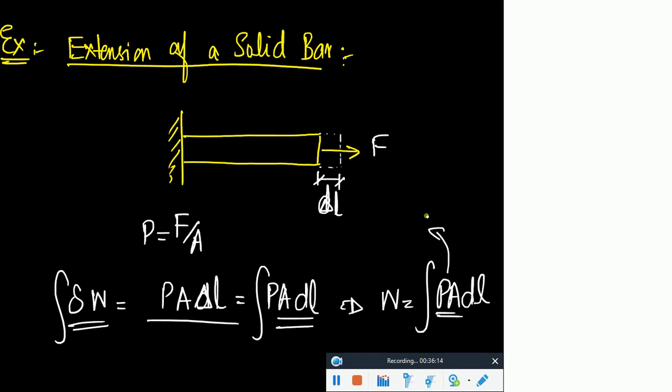So you can say, if I represent that stress as sigma, then sigma would also be equal to F over A. So you can also represent this work as stress into area into dl. Just to clear that ambiguity: you don't apply stress, you apply pressure, and as a result those stresses are developed inside the system. So please use that correct statement.